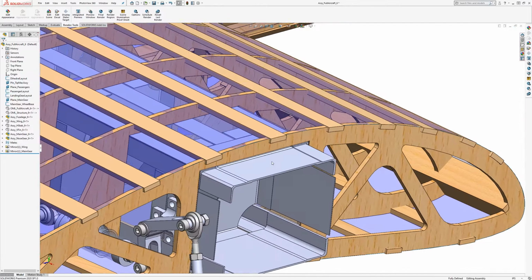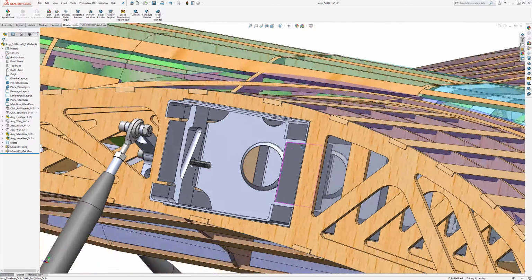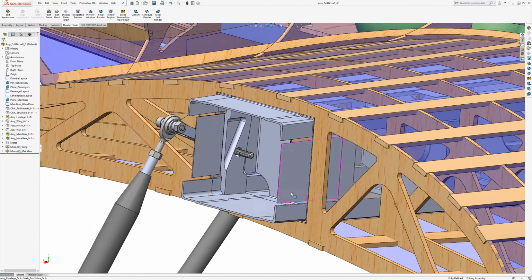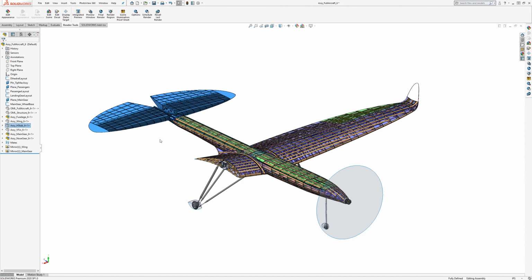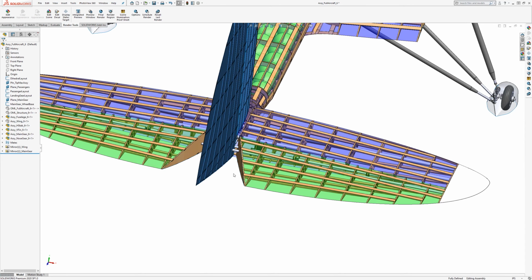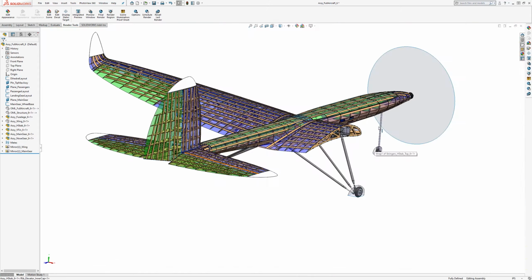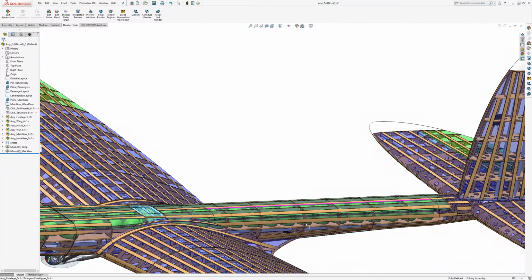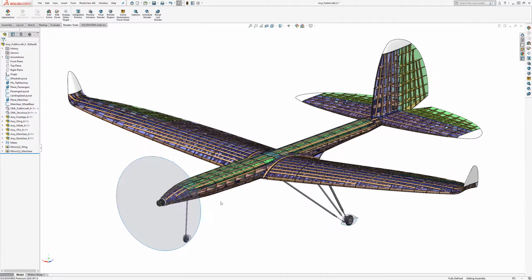As far as the mass properties of the wood portions of the structure, we would go with an initial guess based on past designs, thinking about how many frames and ribs there will be per length and how much they weigh. Now, other than its mass, the wood does not contribute parallel to the metal structure in a way that transports loads throughout the aircraft. It only or almost entirely transports loads from the surface and supported masses to the metal structure locally, so that would be like in series with it.